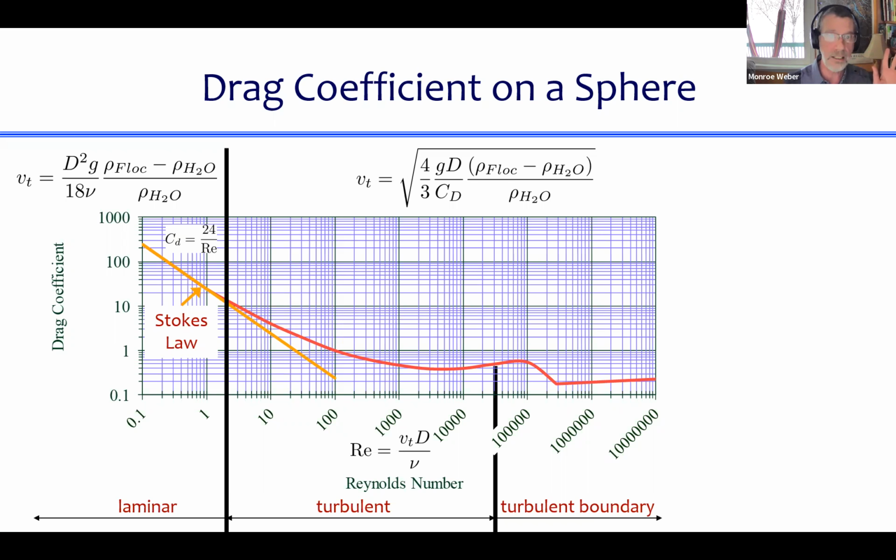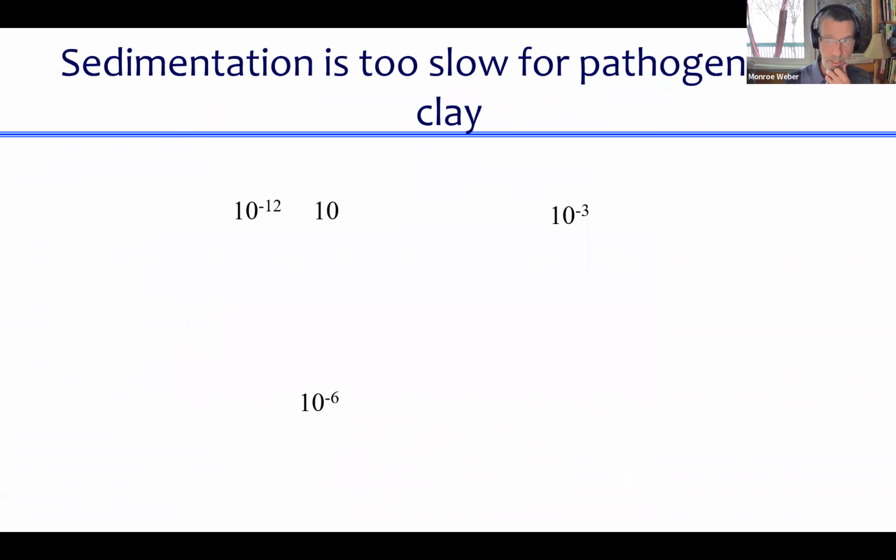And so you can solve for velocity and you get the new equation that I've shown now at the upper left of the slide. And so that is a beautiful, simple equation that only works in laminar flow. It's like the Hagen-Poiseuille equation in pipes. And it's going to be very, very useful for us. We're going to be using that equation plenty of times.